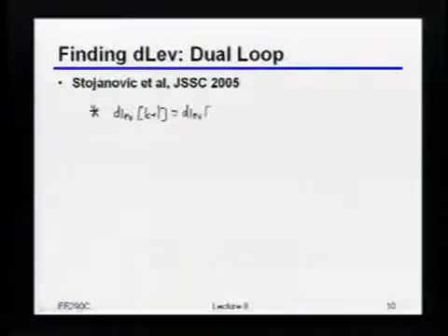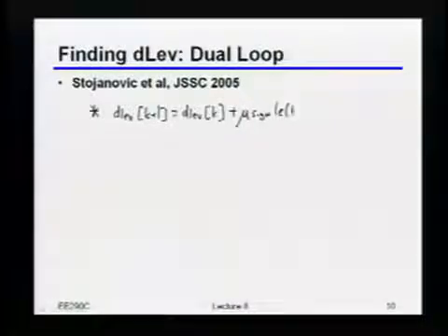Again, as usual, since I want to drive the error to 0, I'm going to build this as an integrator, which in discrete time just means an accumulator. So I'm going to make that loop work just like before: anytime I notice that my error is positive, I move my reference up. If my error is negative, I move my reference down.